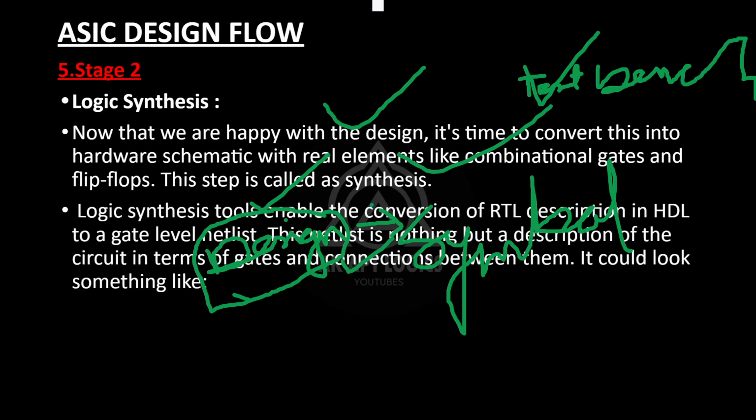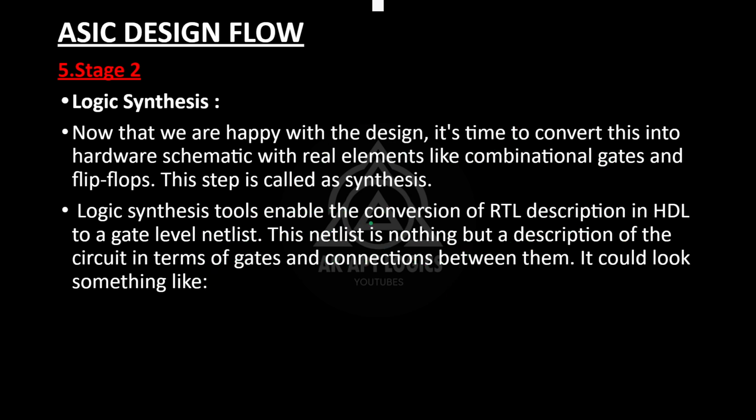Okay, logical synthesis tools. Logical synthesis tools enable the conversion of RTL description in HDL to a gate level netlist. The hardware description, the RTL description in HDL, is converted to a gate level netlist. The netlist is nothing but a description of the circuit in terms of gates and their connections. Netlist is nothing but the description of gates. It is not hardware symbol generation.